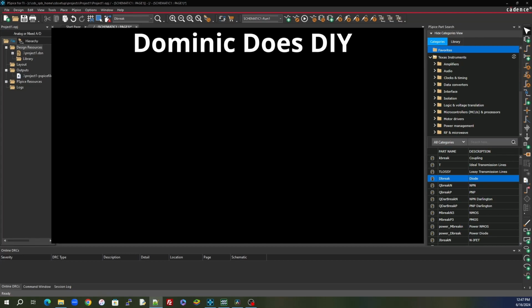Maybe on Amazon you find some energy cells, but they also make power cells. We can pull some serious current from there, like 10, 20, 30 amps from the cell. Usually this is in brushed or brushless motor designs or other things where you want to pull large amounts of pulsed current to run the load. But this does cause a side effect on the voltage rail, which we'll discuss in a little bit, because that same battery powering the load is also trying to power our circuitry, our microcontrollers, our ICs, and other things. And these things have voltage limits on them.